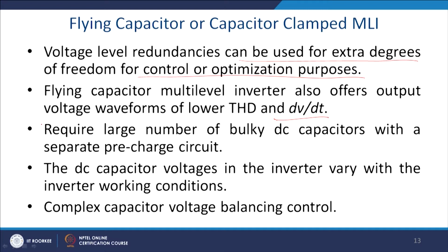One of the major disadvantages is that it requires a large number of bulky DC capacitors with a separate pre-charging unit. So, you require to have a VDC that comes into the picture, and you require to always maintain that voltage.